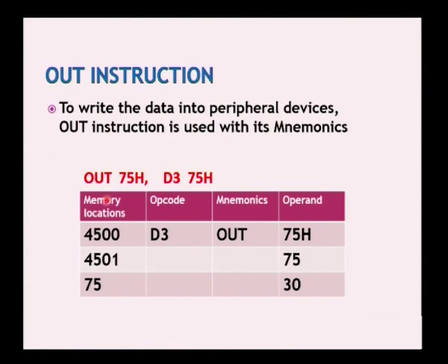So, for this operation, we need the write operation. The OUT instruction is performed with the write operation. This is the format of the OUT instruction, OUT 75H. Actually, in OUT we have to give the port address. So, here we are considering the port address 75H.